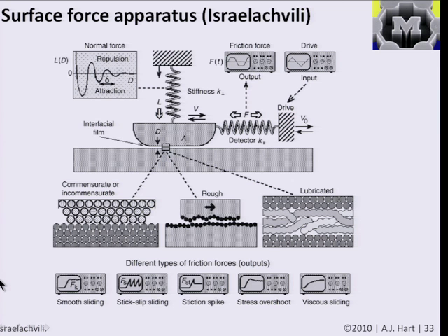So this has led to a lot of interesting research in, for example, engineering coatings for wear and friction, or looking at polymers that are useful for things like repairing knee joints and cartilage. What it gets down to is that the molecular configuration of the surfaces in this gap is very important to how they behave tribologically and how they interact. And you could certainly relate the van der Waals forces, the attractive and repulsive forces, to how the surfaces behave in contact and how they degrade.